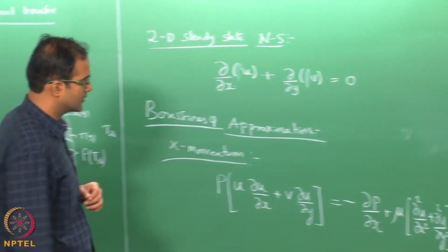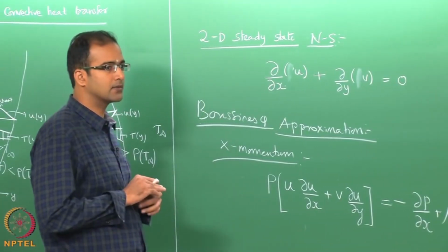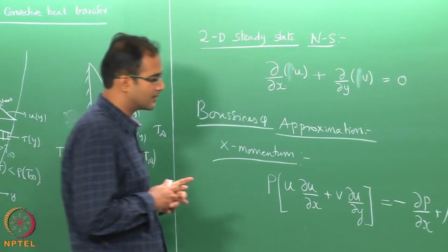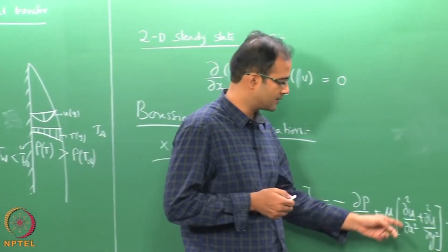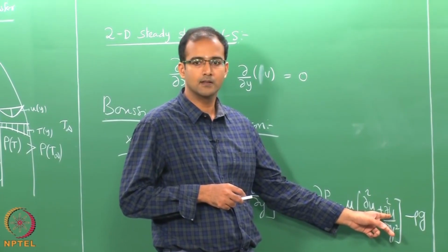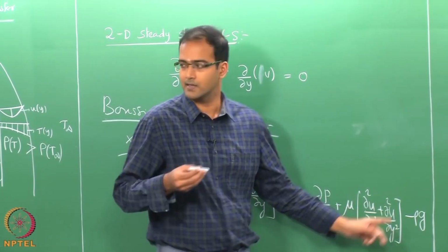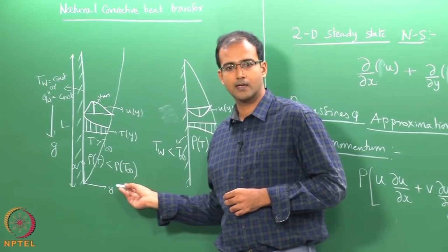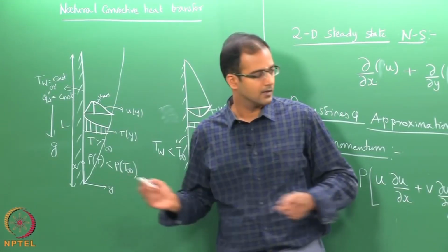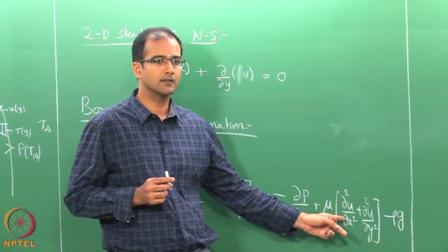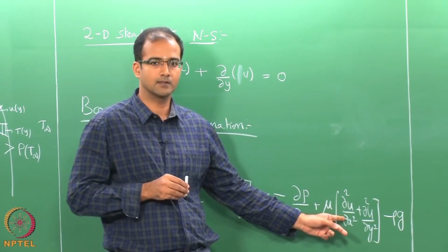Right. So, now once again similar to the external forced convective boundary layer, if you do a scaling analysis, or an order of magnitude analysis, we can show that the diffusion in the y direction, which is the horizontal direction now, Cartesian x, Cartesian y, is much greater than the diffusion along the length of the plate, okay.